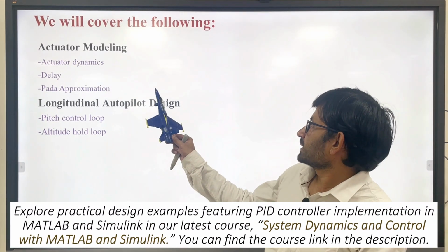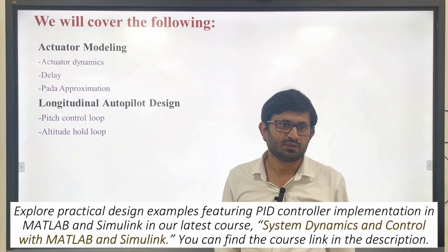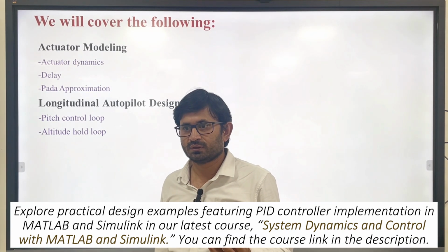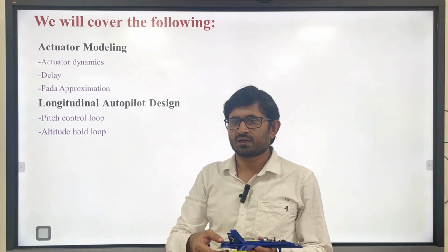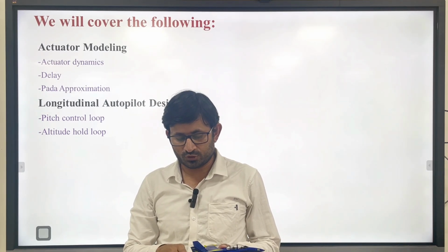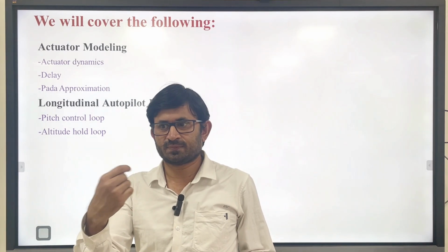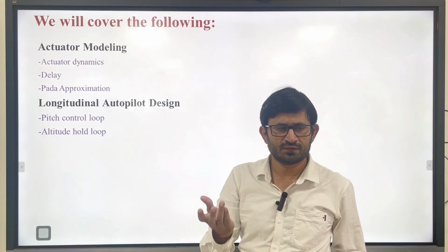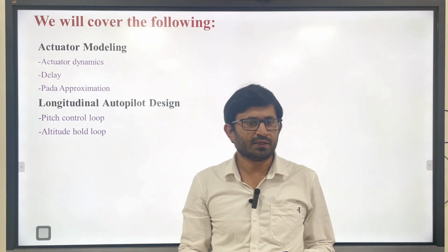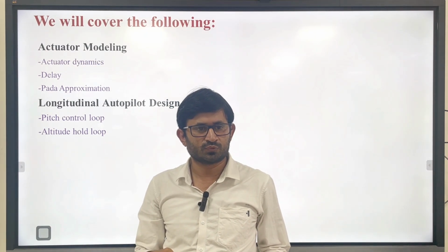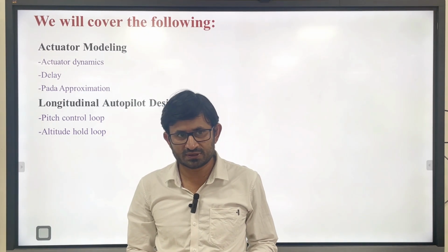In actuator modeling, we will discuss the actuator dynamics, delay, and then how to model the delay using the Pade approximation. Okay, because we already know the aircraft dynamics, but dynamics is involved here also in the actuators, and the actuator will deflect based on the data which is sensed by the sensor, and the sensor has some kind of delay. Okay, so that also we will discuss how to model the delay. And even the computation also takes some time. So overall delay we will consider, because this is a very important part of control system design.